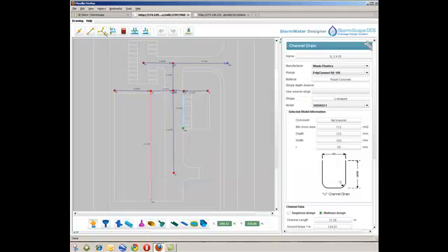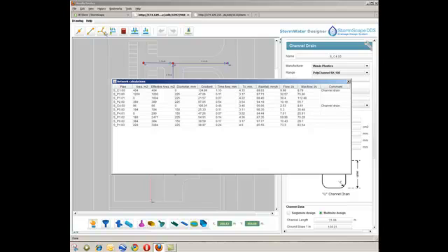The next element to check is network calculations. The results are presented in relation to the pipe runs in the network and include the contributing and effective area in relation to each pipe, the gradient, the time of flow, the time of concentration, rainfall intensity, flow rate down the pipe, maximum flow the pipe is capable of, and comments. In this example, it is evident that the proposed design is satisfactory and does not flood in any part of the network.